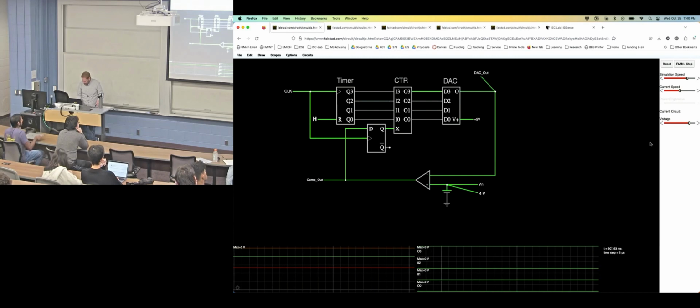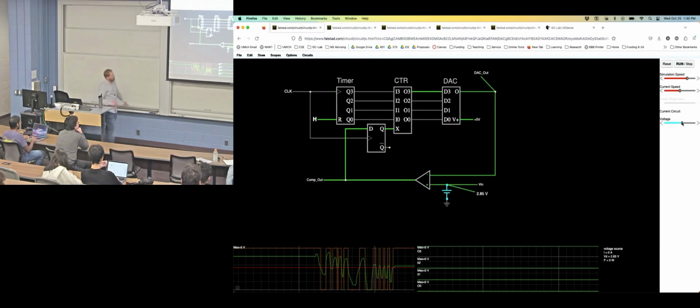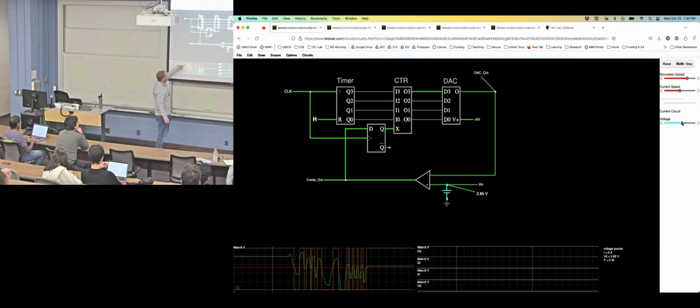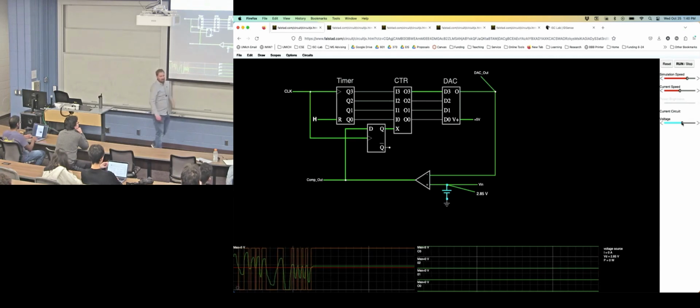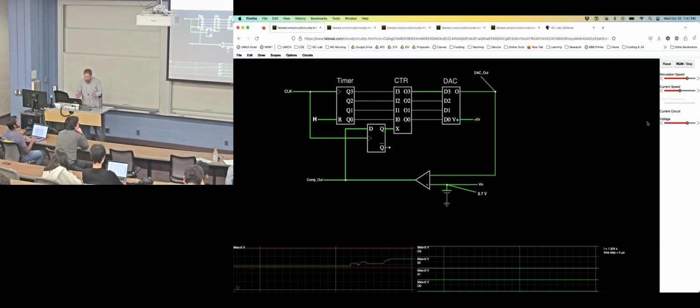All right, so here we go. As you can see, as I move this value around here, I can just arbitrarily choose an analog value. And already you see that the comparator was just switching before I even turned on the device, right? It's already making a decision for that first bit, essentially. All right, so we can choose some value. Let's choose something like that. There's no sample and hold circuit on this because I made it in Falstad, but you would need one typically.